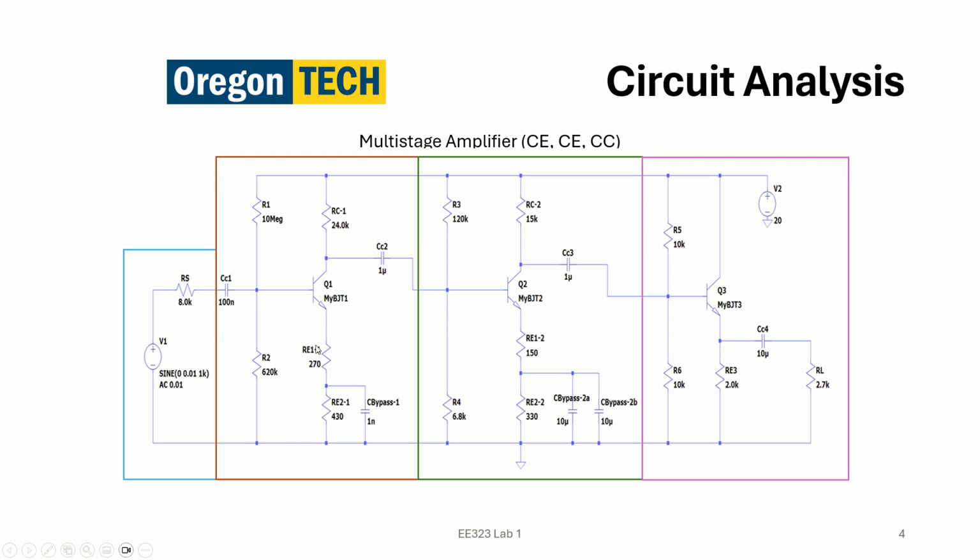So that's why I use the swamping resistor, and I use the swamping resistor on this side. Also, in the objectives, it talked about the minimum and maximum components. Ideally, I would use a 20 microfarad capacitor here, or a 22 microfarad capacitor is a really common value, but I just put two in parallel, right? Because I had to use 10 microfarad and another 10 microfarad, so I just put them in parallel to accomplish the amount of capacitance that I needed.